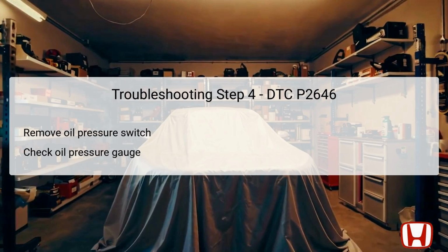These include the pressure gauge adapter and the oil pressure gauge, which must be correctly attached as specified in the diagnostic data. After securely connecting the gauge, the ignition is turned on and the engine is started to allow for testing. Conducting the VTEC test once the engine is running helps capture real-time oil pressure readings.